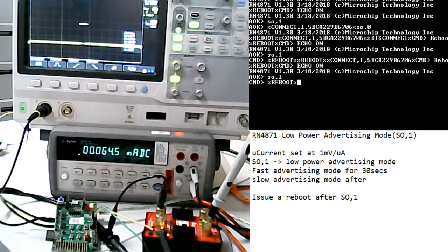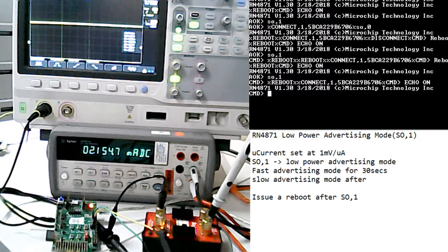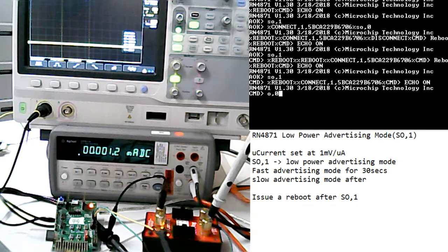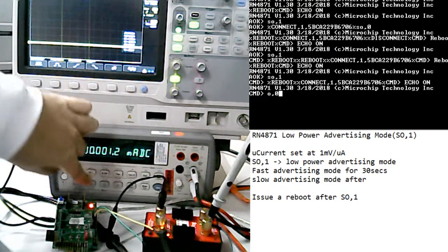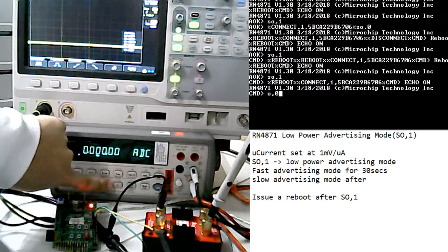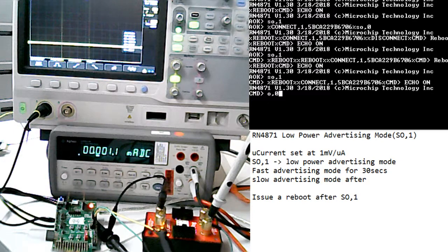So there we go. For the sake of this video, perhaps we should try to look into the dormant mode. So there, the current consumption dropped. Let's see if we can view all. Oh, that's the limit of our multimeter. So roughly around one microamp.